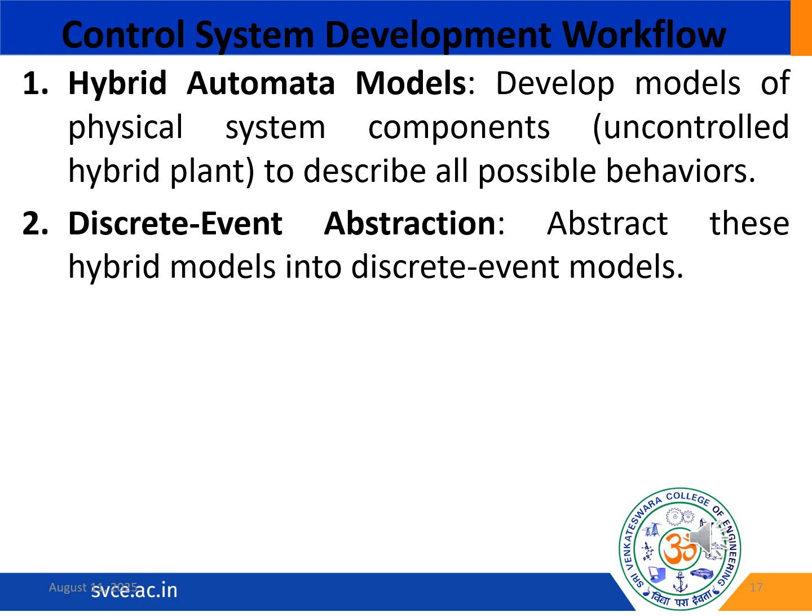The requirements can be related to the functions of the system, and they can be defined in terms of extended finite automata or state-based expressions. So, based on the uncontrolled discrete event plant models and the requirements, the supervisory controller is synthesized using algorithms. From the area of supervisory control theory, these particular algorithms are used, and this supervisor can have a tool. We call it the CIF toolset.